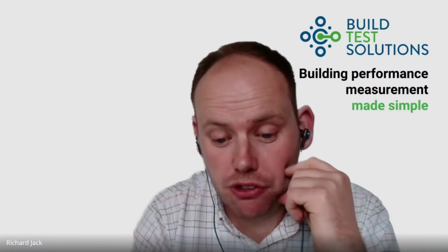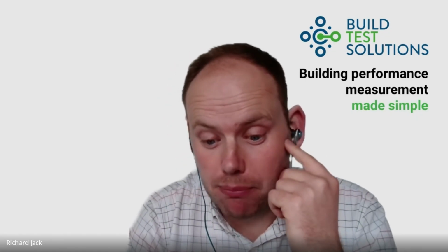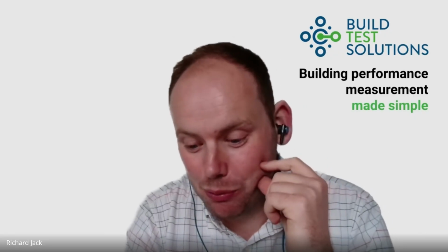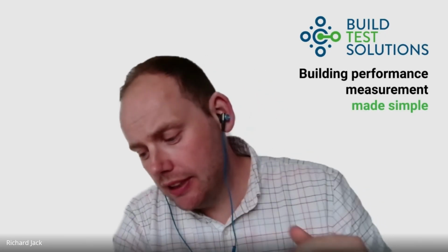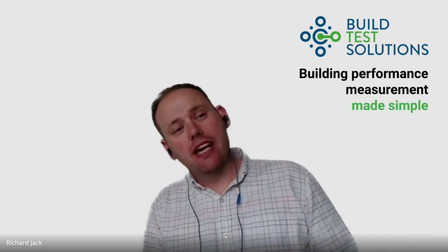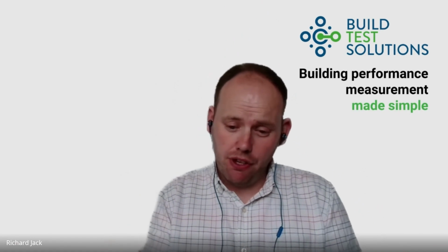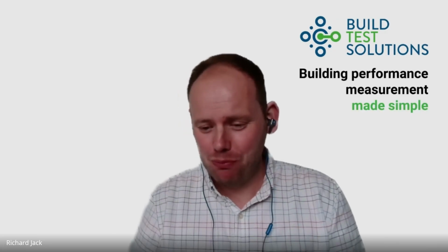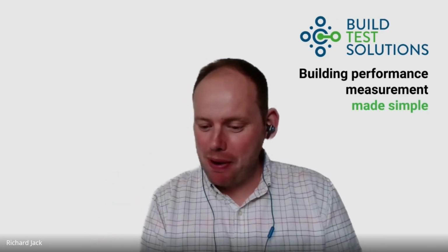That might be helpful. Yeah. So air tightness measurement, you could do any time, and ventilation flow rate measurement. U-value measurements, you need a temperature difference. So in this country, it means winter only. We've got a few customers in Saudi Arabia, and they're never getting a temperature difference where it's warmer inside, but not really relevant for us. And for HTC measurements, the data has to be from during winter, but if you're using Smart HTC Go, you could be using historical. All smart meters have 13 months of history on board. Someone loses confidence that the right number is 13 months, but it's more than 12 months, it's absolutely certain. So you can go back into the previous winter and use that data at any time.